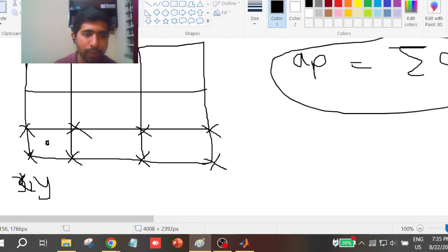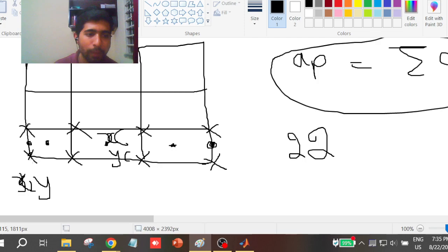Now this is centroid, this is centroid, this is centroid. For 3 control volumes you will get 5 centroids. So in general, for example, if I want 20 control volumes, I have to define 22 centroids, plus 2. Because here I have 3 control volumes and 5 centroids, right? 3 internal centroids and 2 boundary centroids. So this I will call xc, x of centroid, and yc, y of centroid. This is how I usually name it. Whereas the corner grid points I write as x and y. You can follow any convention, but this is the general thing.